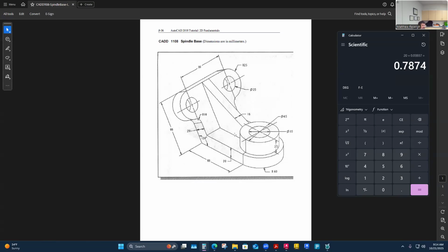Maybe it can't hold up to the load, and so they put what's called a gusset in here to additionally support. And it looks like they run this gusset clear over to the cylindrical features. It's almost like they're taking forces that might be exerted on this inner bend and fatigue it potentially. When they apply this gusset in here, you can push some of that force over to the cylinder and balance out something that might break under some loads, and now it won't.